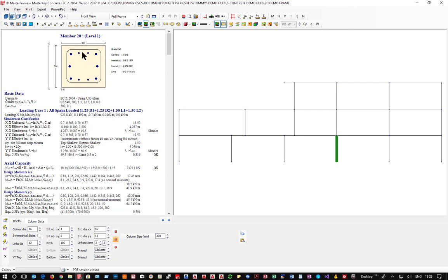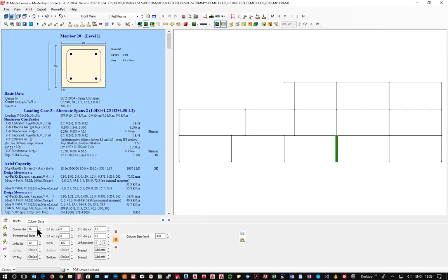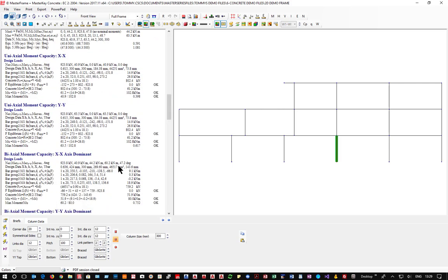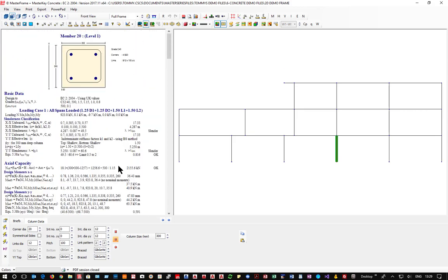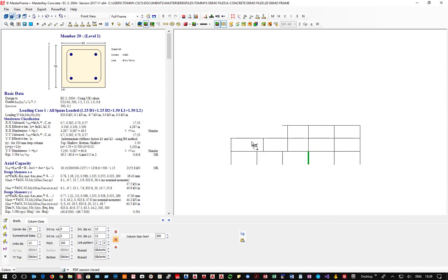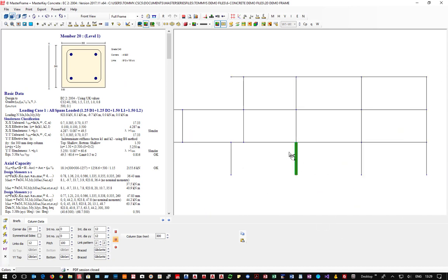Now we are working because we're within a distance from a restrained bar for these unrestrained bars. I would much prefer to see it as a symmetrical reinforcement and symmetrical 16s in the corners, 20s in the 12s in the edges. But as you can see, we can go just purely for 20s, simpler cage, and away you go. And again, we're looking at this because we're in slender members due to some components of our design. We do need to put in more onerous reinforcement.